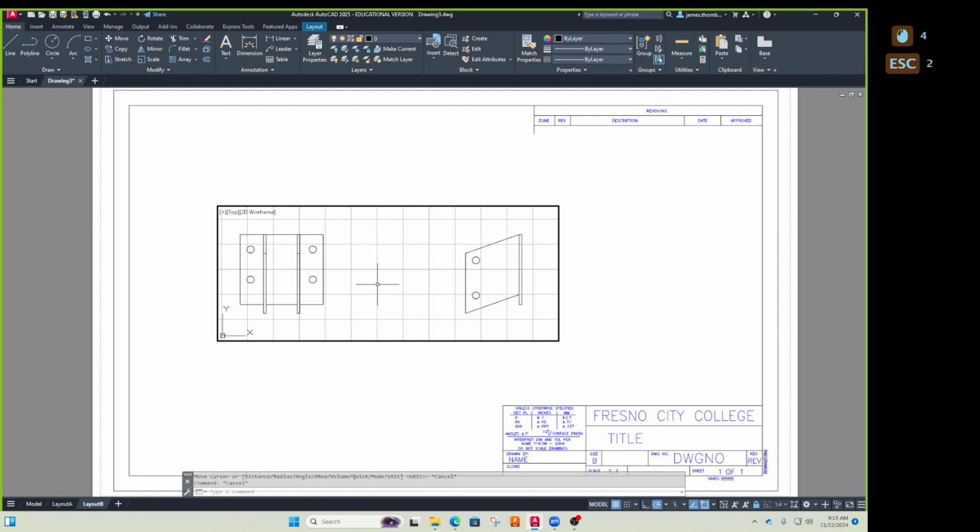And in order to change from paper space to model space, you have to be out of commands, and then you can double click to change, or you can click the button here that says model and paper, or you can type PS to go to paper space, or MS to go back to model space. So remember, at least 3 ways to do everything.